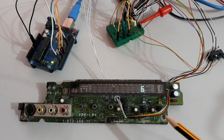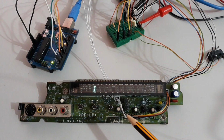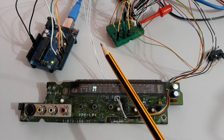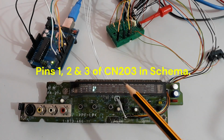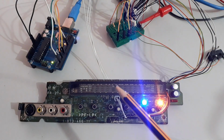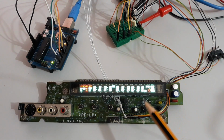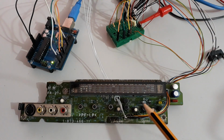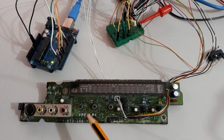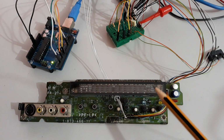I did not create code to read the keys present in the panel, but these keys have as output these 3 wires, and it is a set of keys with resistors in series. When you press one key, you have, for example, 100 ohms. When you press another key, you have 500 ohms, and so on.